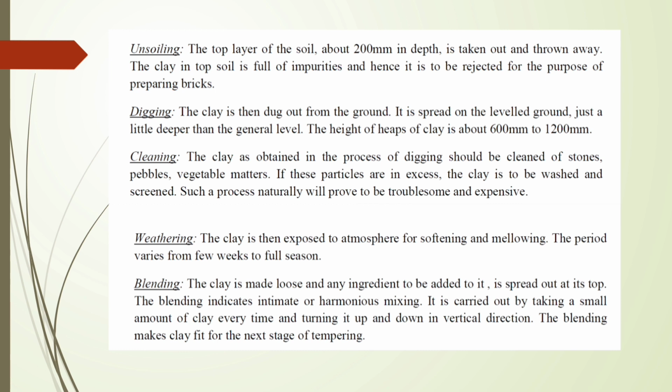Digging. The clay is then dug out from the ground. It is spread on the leveled ground, just a little deeper than the general level. The height of heaps of clay is about 600 mm to 1000 or 1200 mm.